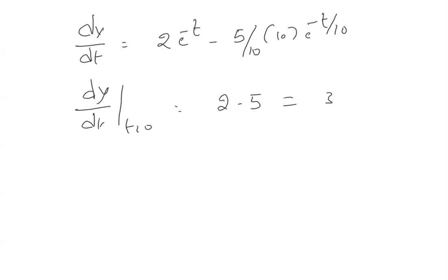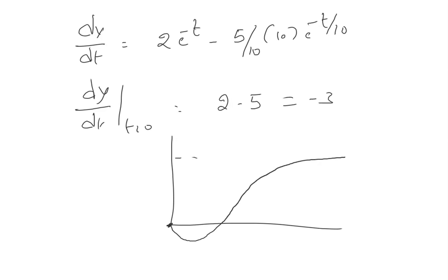So it is a negative slope. If you take the response, initially it starts with a negative slope and then it settles at the gain. What is the gain that you are getting for this one? For the second transfer function, the gain is 2 minus 5 by 10, which is 15 by 10, which is 3 by 2, or 1.5. This is y with respect to time. So this is an inverse response with positive gain.